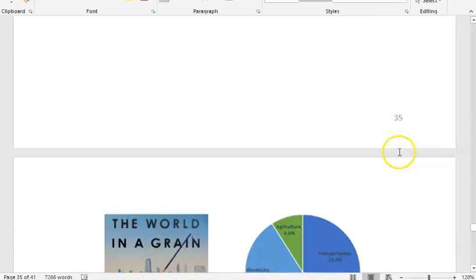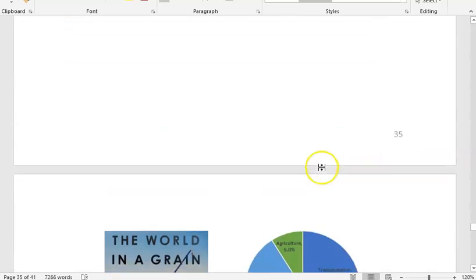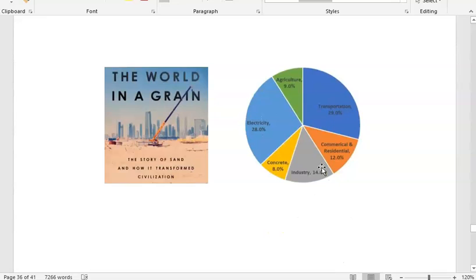Okay, concrete represents a major sustainability risk. So why does it represent a major sustainability risk? There are two reasons. One, we're running out of sand. We're running out of good quality sand that we can use for concrete. So we need to use alluvial sand, or sand that comes from rivers. We can't really use desert sand. This is why Australia exports sand to Saudi Arabia. They have lots of sand, they just don't have good sand that can be used in concrete. And the world collectively is running out of sand that can be used in concrete.